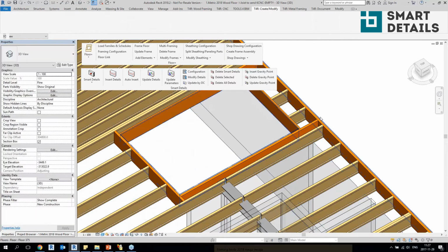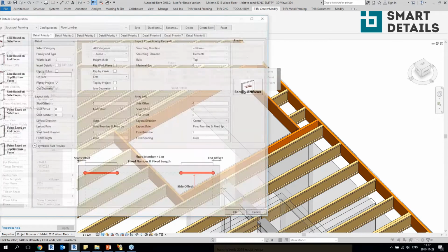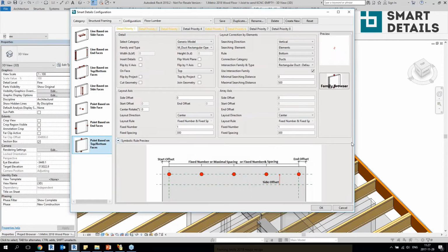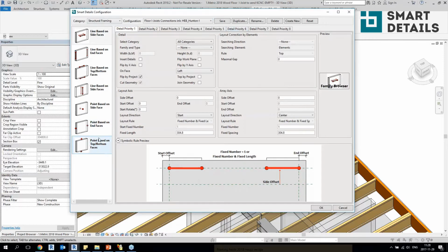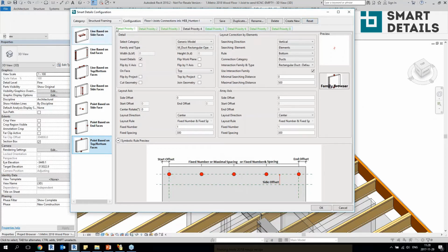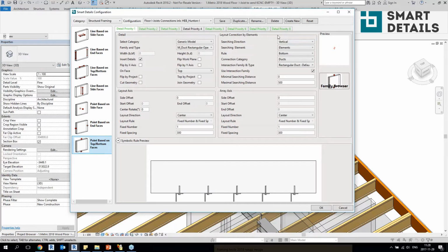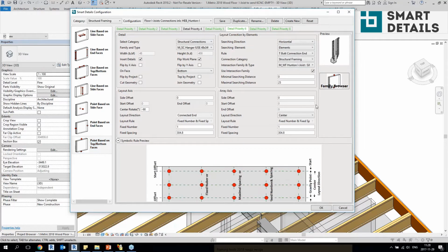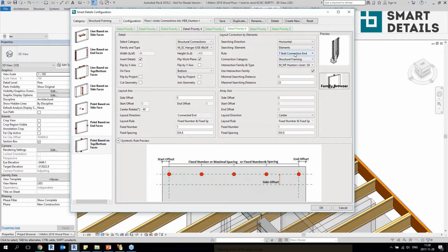so we can add those details automatically to different element types, because in these element types I have configurations for the details where we can predefine everything that we will add. So you can see that these green rules I'm using. So this tool is a very powerful tool that adds details to and searches elements in various directions, adding these eye joists that you will see in the T connections and butt connections and all kinds of situations.